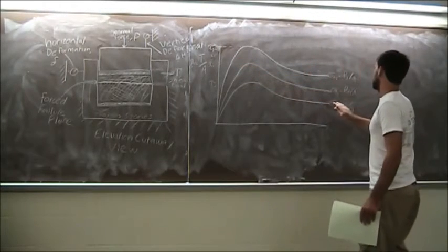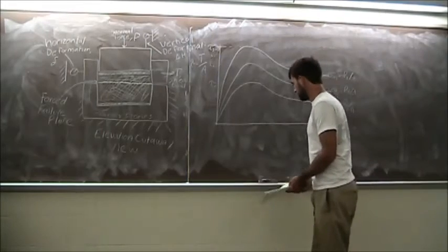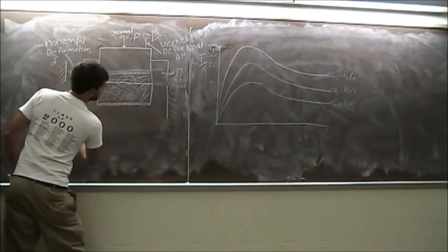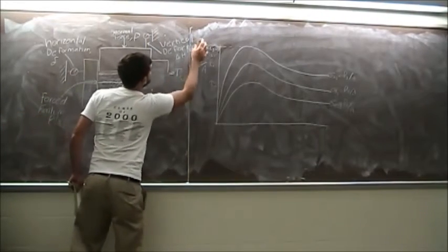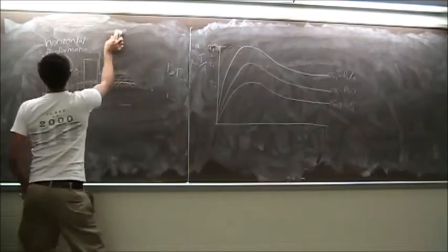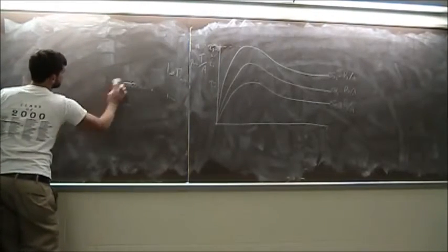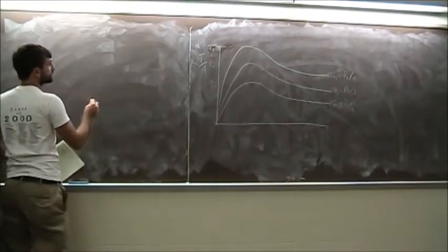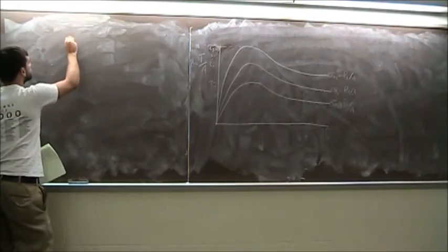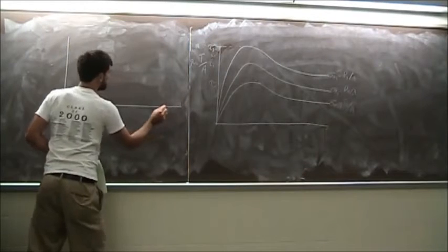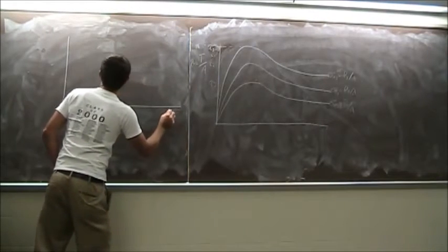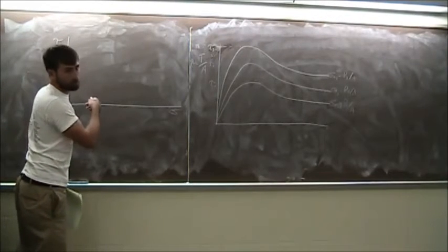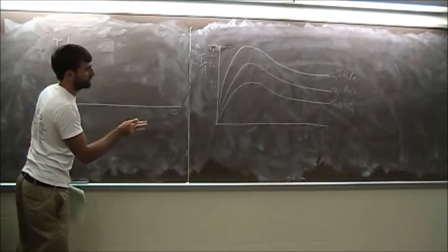But okay, regardless of that, now we have shear stresses and normal stresses. So from before, I'm going to leave that up here. I'm going to go ahead and get rid of this. So what we've been looking at for the Mohr plot is a plot of shear stress versus normal stress. So we have the points now. So let's go ahead and make one of those plots. So this is normal stress, and this is shear stress. So I'm just going to plot values here that are approximately corresponding to what we have there.